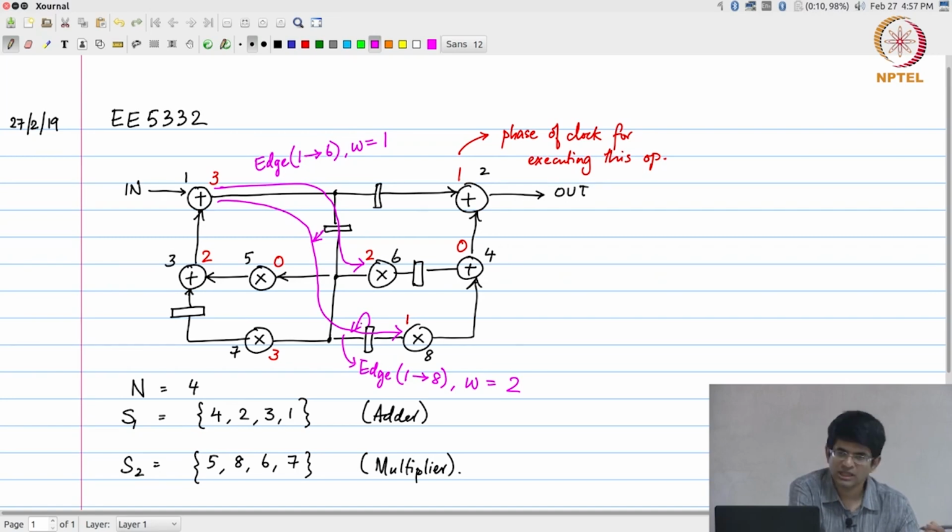Okay. So, I have drawn it in this fashion so that it is compact and easy to visualize what the structure looks like, but in order to actually interpret what all the different edges are that need to have implementations when you fold the architecture, you need to take the operational nodes, what are the additions that need to be done, what are the multiplications that need to be done, and find out the connections between them directly, and how many sample delays are on those edges between them.